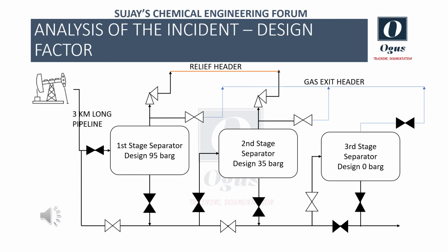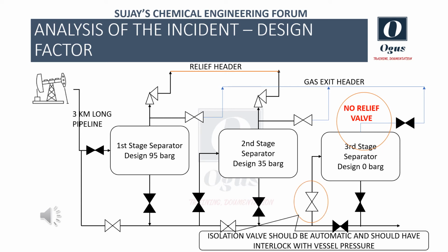The major error was the lack of a relief valve on the third separator. Moreover, all the 3 vessel liquid inlet valves should have been automatic shutdown valves equipped with interlock with the vessel pressure. A hazard and operability study or HAZOP should have highlighted these design errors.